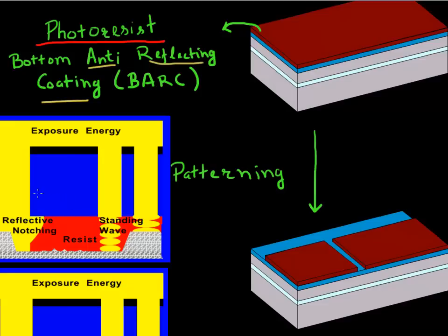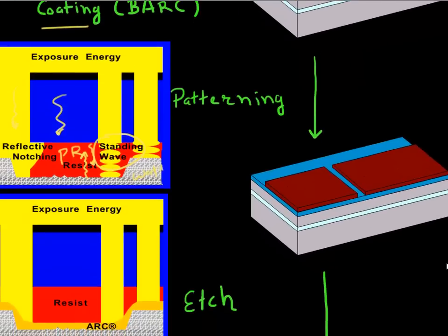So if you place your photoresist on top of your wafer, when you shine light, it will reflect back from the surface, and then reflect back again, and it will create these standing waves in the resist, which are bad for the fidelity, and they lead to essentially feature loss or loss of resolution in your resist. So to avoid that, you place an anti-reflective coating.